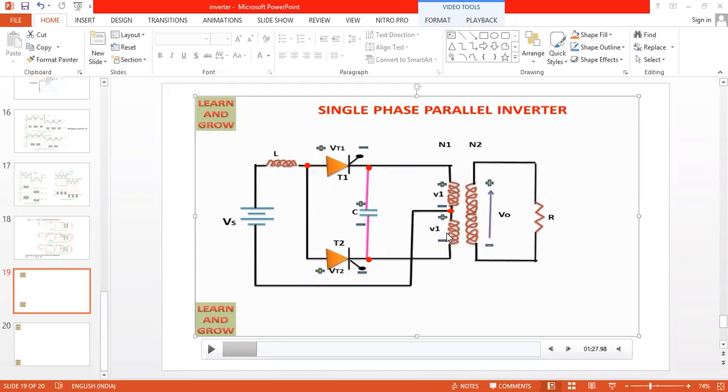So why are we using the inductor? That is the question. Without the inductor also, current starts to flow through the SCR. Why is the inductor specially shown? The inductor passes the pure DC current. The inductor acts as a short circuit to DC current. If the supply has any harmonics or unwanted AC components, or any AC current is present because the supply is not pure, then this inductor will filter out those AC components.